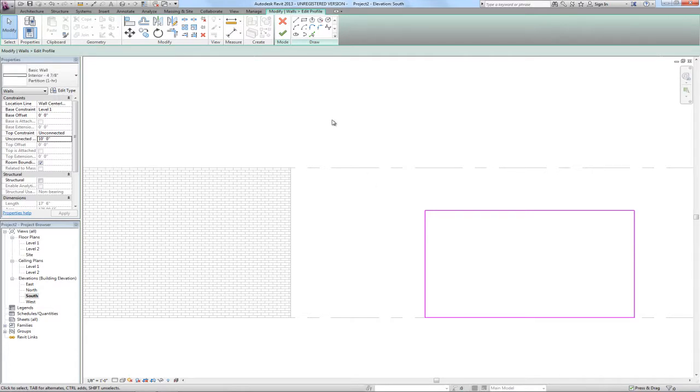Alright, so while we're in this sketch mode, we see some line draw tools that we can use here. We'll click the straight line option, and then we'll just draw the sloped portion of the top of the wall that we want. However, before we click the green check mark to finish this profile, we have to have one simple profile.